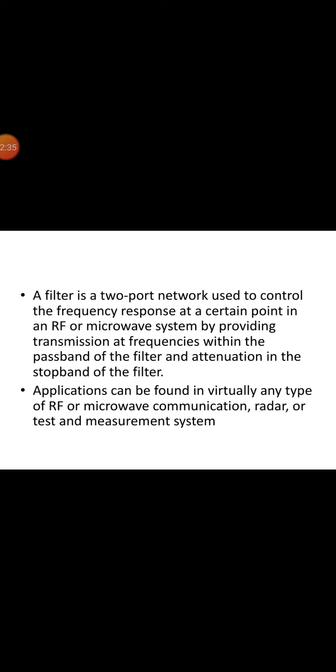A more modern procedure called the insertion loss method uses network synthesis technology to design filters with a completely specified frequency response. The design is simplified by beginning with low pass filter prototypes that are normalized in terms of impedance and frequency. Transformations are then applied to convert the prototype designs to the desired frequency range and impedance level.